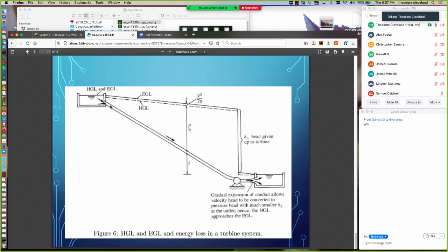Usually the penstocks are pretty large diameter because the goal is to keep the velocities kind of low. At least with the type of turbine here, a reaction turbine, there's no convenient way to extract energy from high velocities. It can't be zero, the water has to move. So the pipelines are usually fairly large diameter.